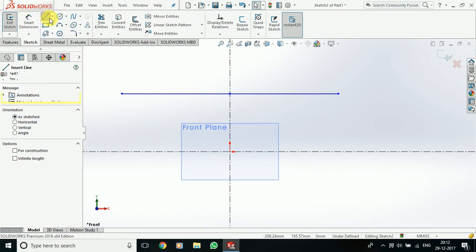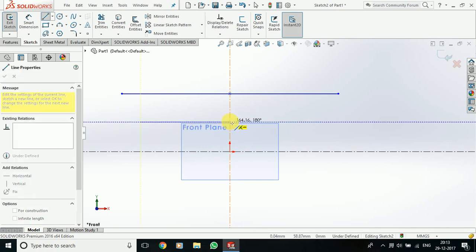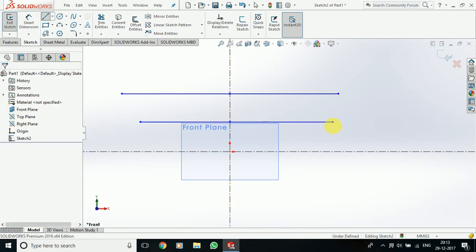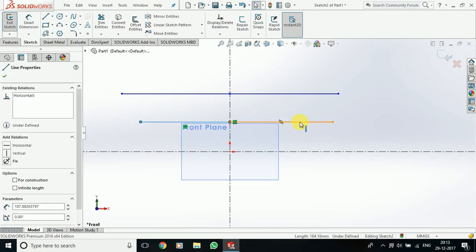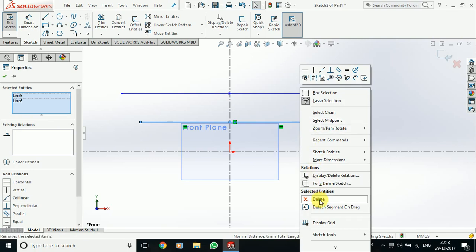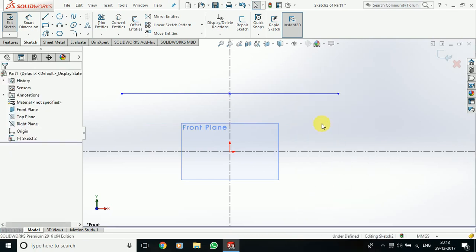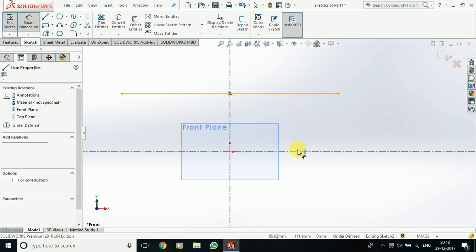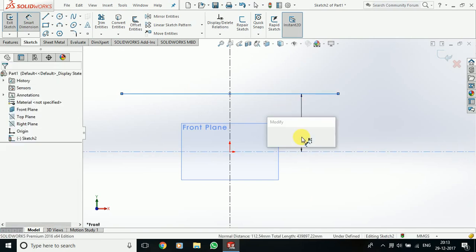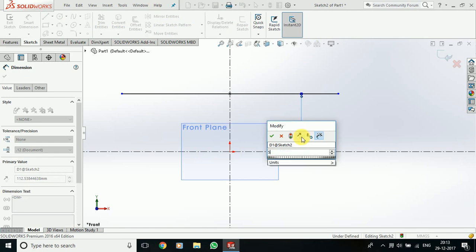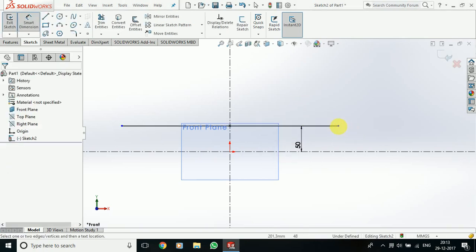If we use the simple line to make the line in both the directions, then first we have to make a line from here to here and then from here to here. To make 2 lines it will take some time. So to save this time we can use the midpoint line. It can be defined by providing the dimensions as you used in simple line, like it's 50.